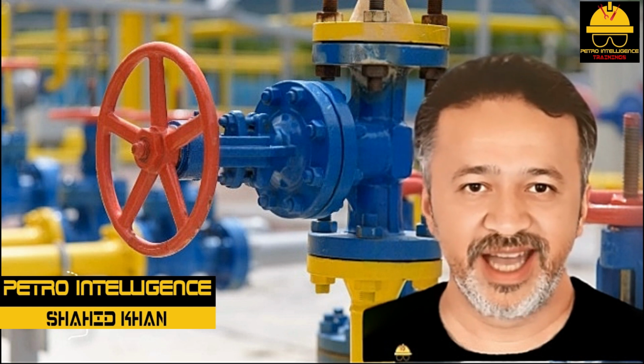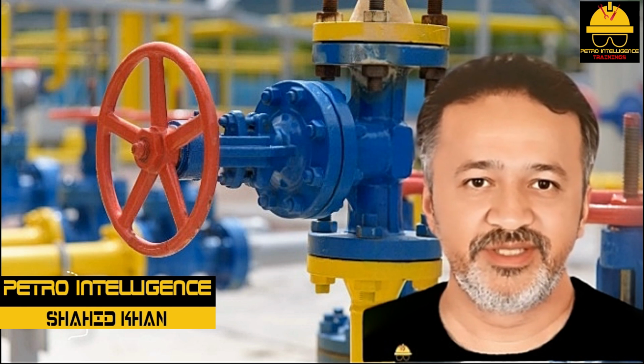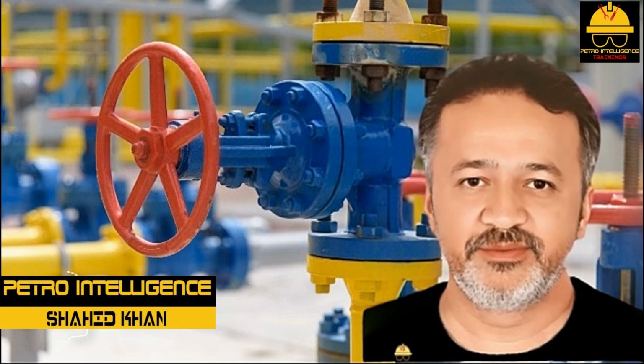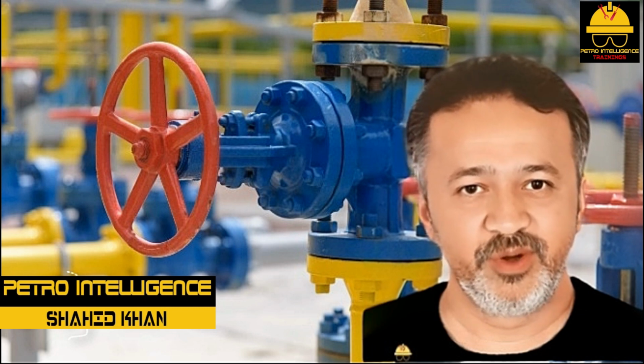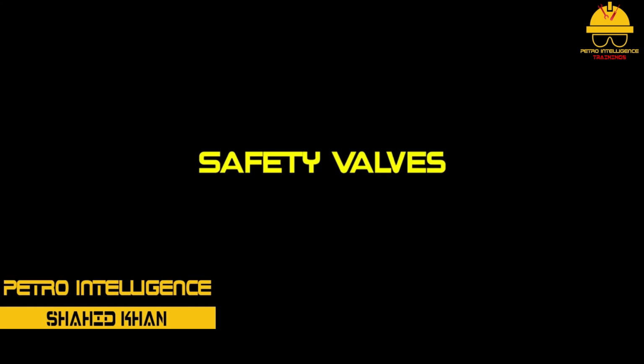Some relief valves have a handle on the side to check the function of the valve. This is a maintenance function, however, and the technician should not use this lever. The two advantages of relief valves are that they will reseat as soon as the pressure drops below the relief pressure and the spring tension is adjustable.